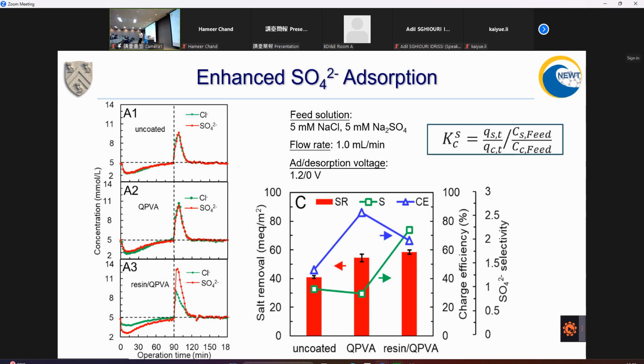The smaller the particle size is, the more perfect the particle and polymer substrate interface is. So when you have a very big particle size and you embed it into a polymeric thin film, you often have large defects around the particle, so your cations will go, this is an anion exchange, cations will go straight through, so you lose charge efficiency.